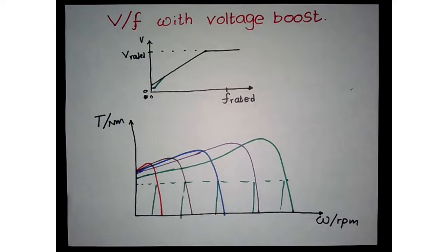Of course, there are other advanced methods that you can use for torque control: field-oriented control, direct torque control techniques, indirect torque control, indirect field-oriented control, which relies on sensors and some kind of estimation of flux or current, to achieve control of the machine.